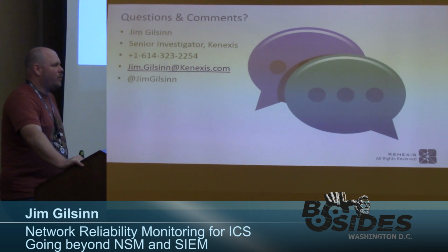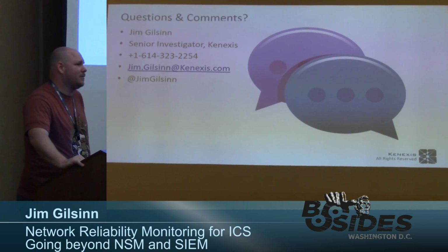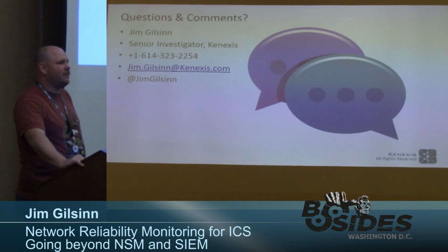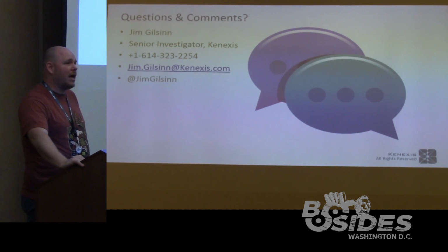We haven't noticed malware down at that lower level, but we've noticed strange things happening. Let's just put it that way. Some of the industrial controllers have USB ports on them, and when the operator has to sit in front of that system for 8 hours a day, and they want to charge their cell phone, but they haven't been told not to plug that into the HMI or into the controller itself, they will do stupid human tricks. And you will sometimes see weird things happening to the network.